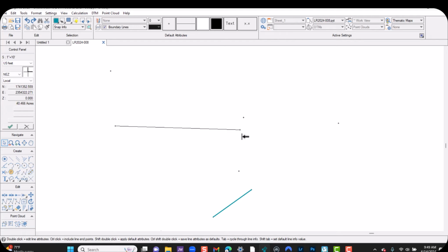So with regard to measuring between two points, for example, I can click on the line tool, click on a point and just drag it over and click to the other point. And look, I have a distance here of 23.140 feet. So I just hit the escape key and that's gone. So I can measure that distance easily between those points.